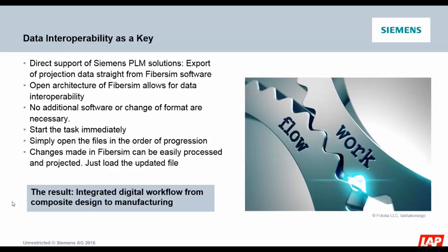As a conclusion, you can say, project the ply boundary for the proper alignment on the tool, and validate that the correct ply is being placed at the correct time, and improve the quality of the layup. This means optimized layup being much more accurate, more flexible, and faster.